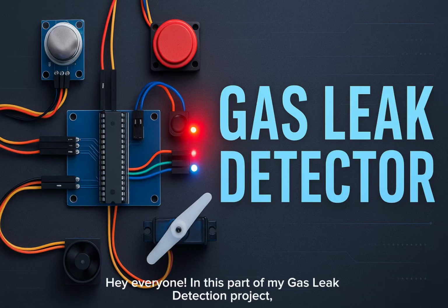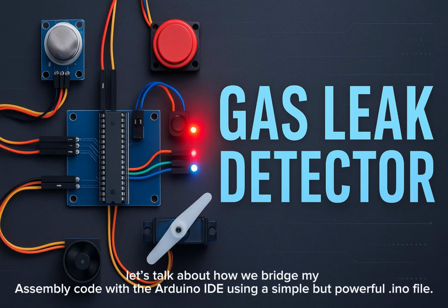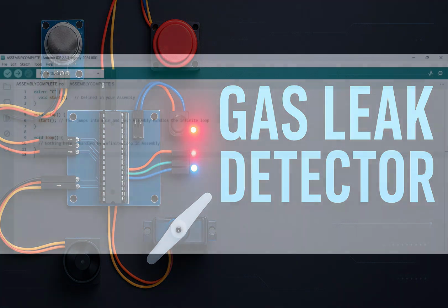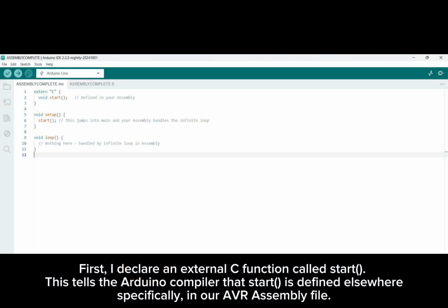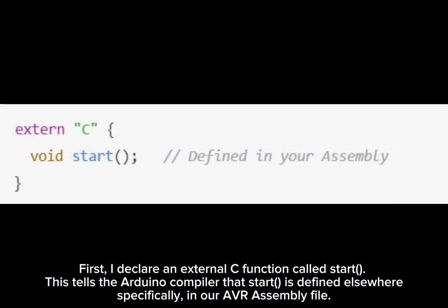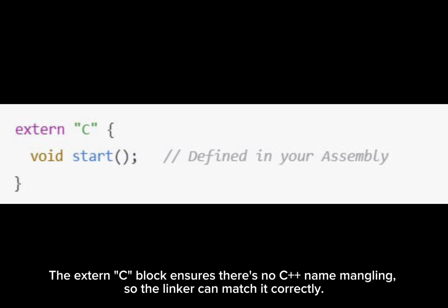Hey everyone, in this part of my gas leak detection project, let's talk about how we bridge my assembly code with the Arduino IDE using a simple but powerful INO file. First, I declare an external C function called start. This tells the Arduino compiler that start is defined elsewhere, specifically in our AVR assembly file. The extern C block ensures there's no C++ name mangling, so the linker can match it correctly.